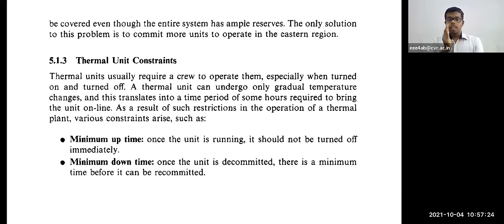So what they are telling is, once the unit is decommitted, there is a minimum time before it can be recommitted. So after 10 o'clock when it is off, there is a minimum time to let all the process be cooled. Say for example, the boiler also might be cooled, and the water inside that boiler also has to be replaced. Why? Because if it is not replaced, then scale formation will be there in the boiler.